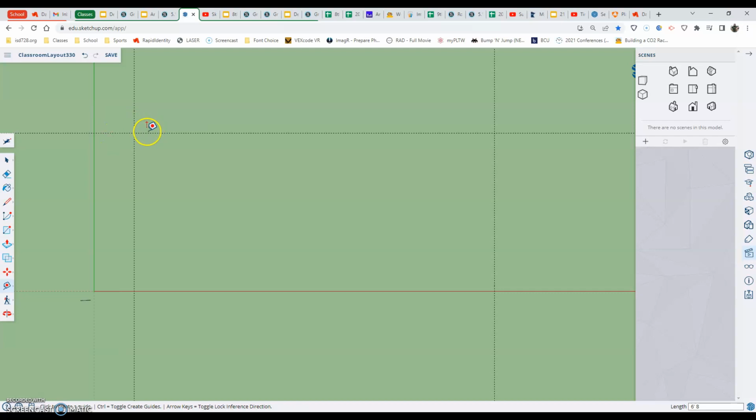Now that I have that, the next thing I want to do is use my previous guideline on the north wall, select that with my tape measure, slide up, drop that, and put that down at 2 feet, 8 inches. Enter. The next thing is I want to come in and go from my east-facing wall 11 feet, 4 inches. And I just noticed in the last clip that I didn't have to actually have a space in between. It entered the right piece.